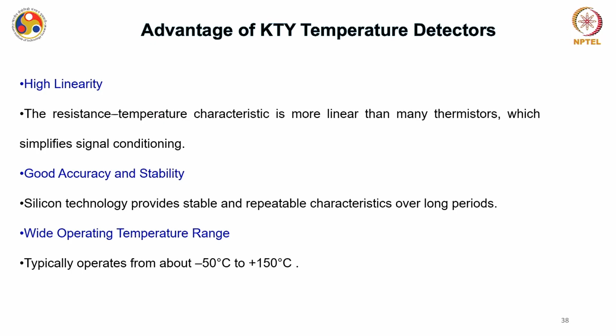And they have a limited temperature range. We have devices which can handle temperatures beyond 600 or so, but then they cannot measure anything less than 600. So both platinum and tungsten devices have their own merits and demerits, but mostly they have a limited temperature range.